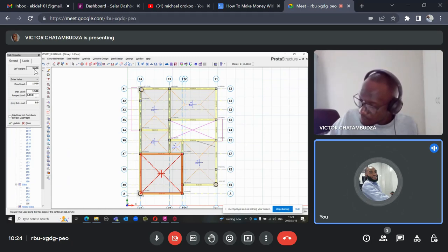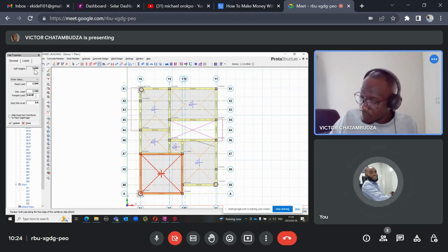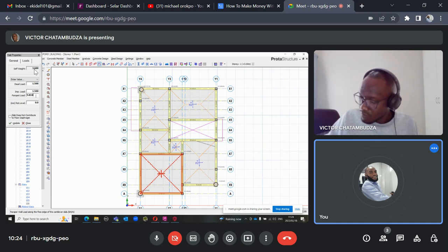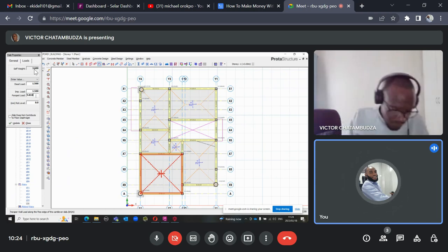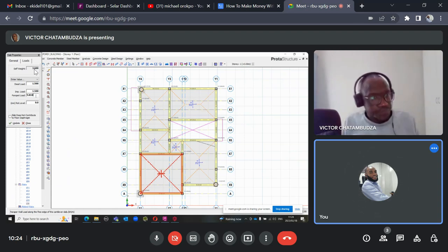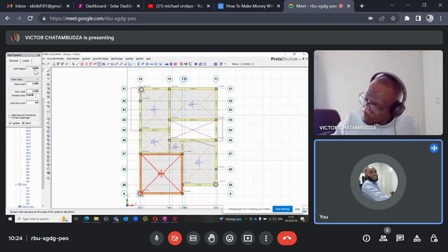Now, on this one, we will have to multiply it by the height of the floor, or let me say of the building, where the block is meant to occupy, or let me say contain. So if we are using 3 meter as our height of building, if we times this 3.47 by 3 meter, that gives us 10.41. Now, knowing that block wall we're not going to extend to that kind of height, because block wall will stop at the beam bottom, right?